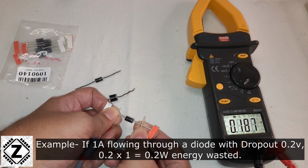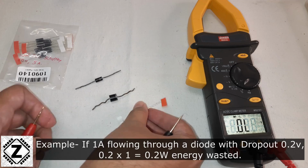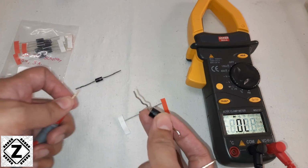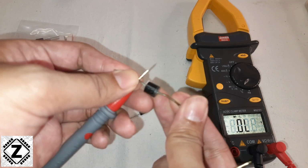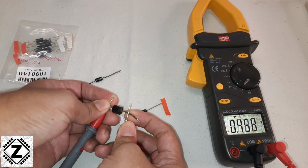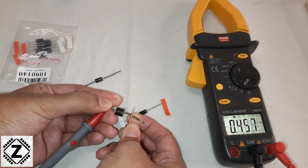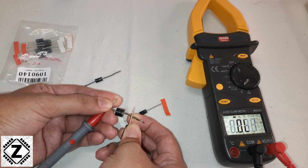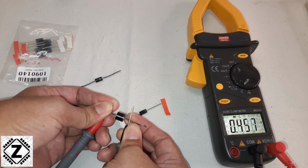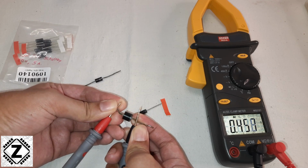All right, so I'm going to explain how to convert these values into wasted energy or wasted heat. Okay, say for example, if we have a project where we are using this cheap little general purpose silicon rectifier diode which is dropping half a volt. All right, and let's assume that we have 1 ampere flowing through this diode, or you can say 1 ampere flowing through your circuit, which includes this diode.